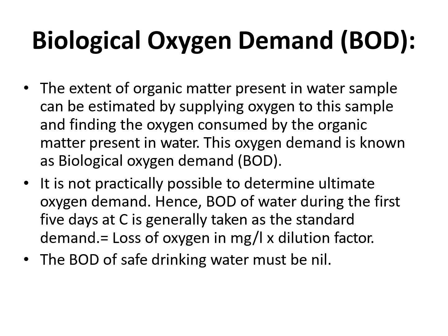first one is BOD. BOD means biological oxygen demand. The extent of organic matter present in a water sample can be estimated by supplying oxygen to the sample and finding the oxygen consumed by the organic matter present in the water. That is called the biological oxygen demand.